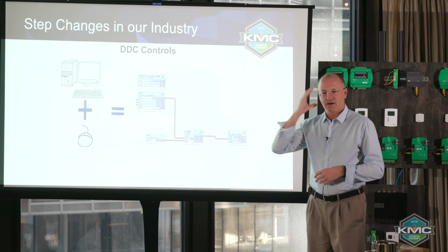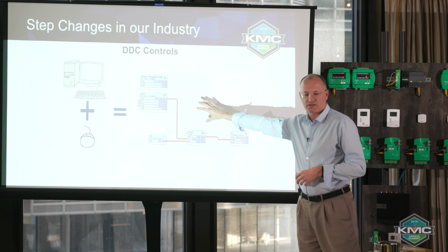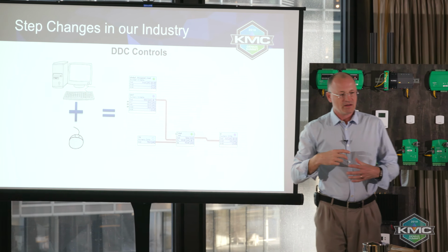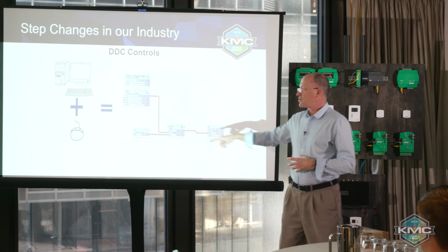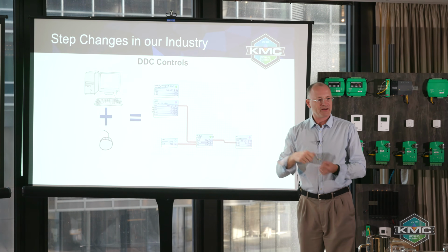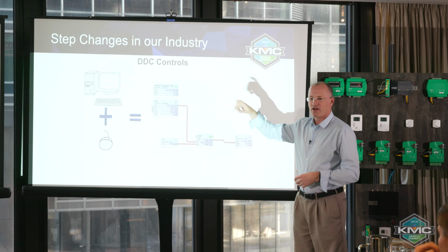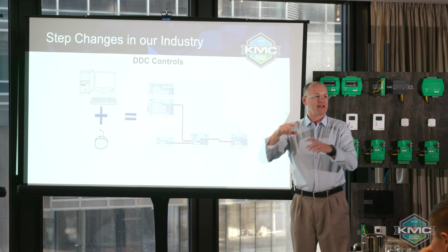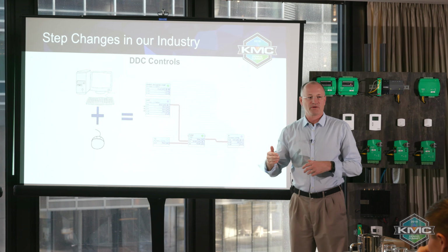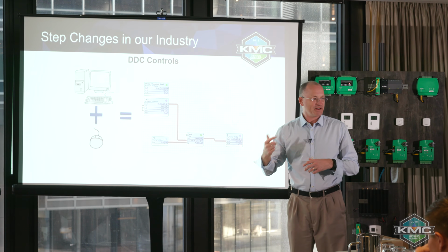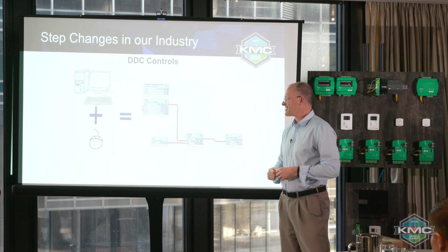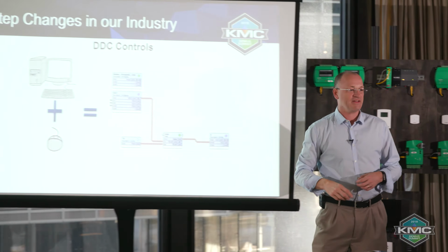But the aha moment was that if I had to do this control sequence for this room, chances are really good that I would draw it once, very similar to the wiring and the tubing, and then copy and paste and then link, link, link to get the next one done, and then rinse, repeat, and continue that process for all 500 VAVs.